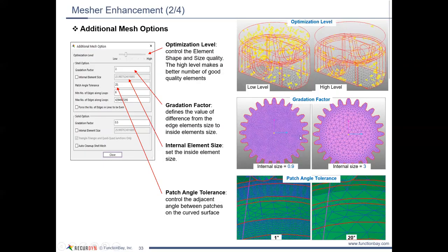If you do see a difference in the results, then maybe head back towards the direction of the starting point. But you just need to experiment a little bit till you get the right combination where you're going to get a faster simulation with fewer elements, but still get the accuracy.